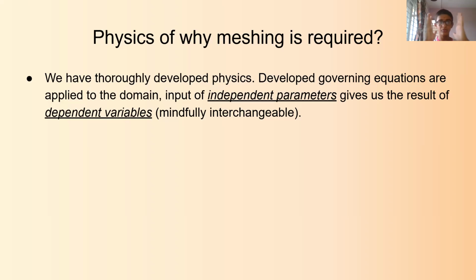Then if we are going to compress it, it may deform in some other directions. Since it is going to reduce its length in the axial direction, in the transverse direction it will bulge out. So the result of interest will be, if there is a deformation, how much is the total deformation. If there are directional deformations available, we can check the specific direction deformation, such as in y direction, z direction, etc. Then we can have stress, we can have strains.